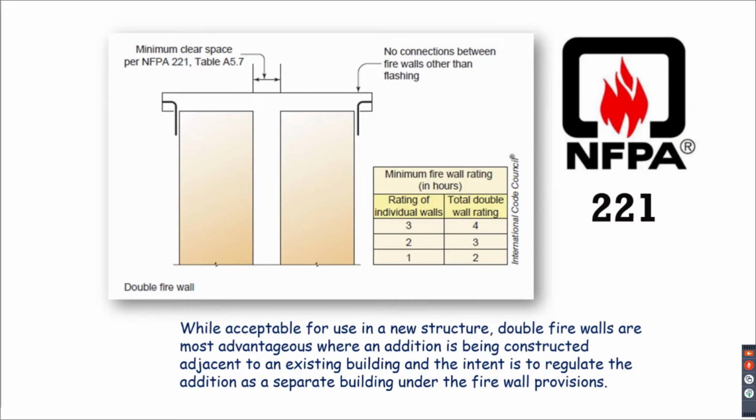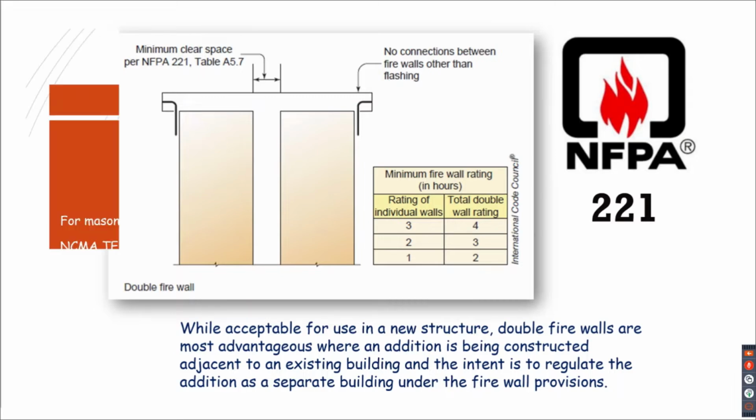They give a lot of great examples of how these walls could be constructed, and they even give some examples of how you might design the openings, because again, our firewall is supposed to have horizontal offsets. How do you put a door in a firewall that's basically 2 walls adjacent to each other without a horizontal offset? So we do look at that obviously when taking that into consideration. But look at the end of 221 for some examples for that as well. So we'll keep moving here.